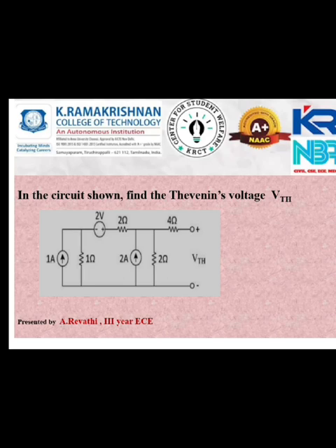Thevenin's theorem states that any linear circuit, no matter how complex, can be simplified to an equivalent circuit consisting of a single voltage source with a series resistance connected to the load. Here we are going to calculate Thevenin's voltage. Thevenin's voltage is nothing but the open circuit voltage across the load terminal.